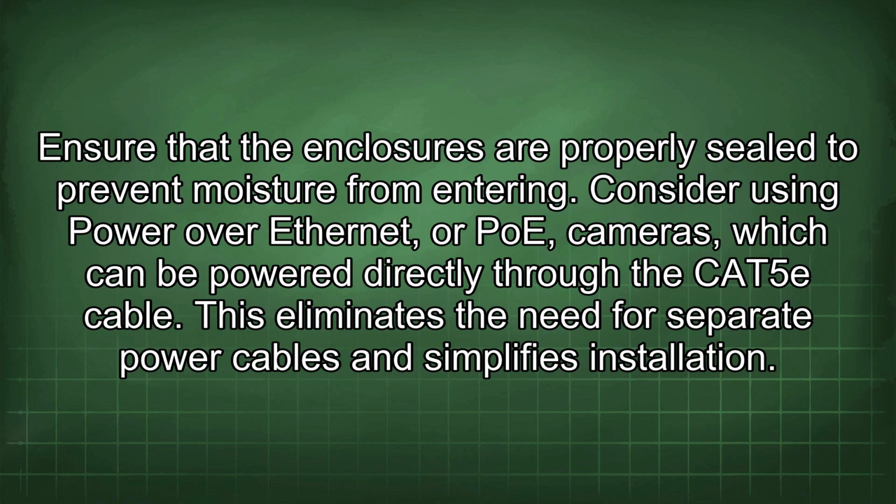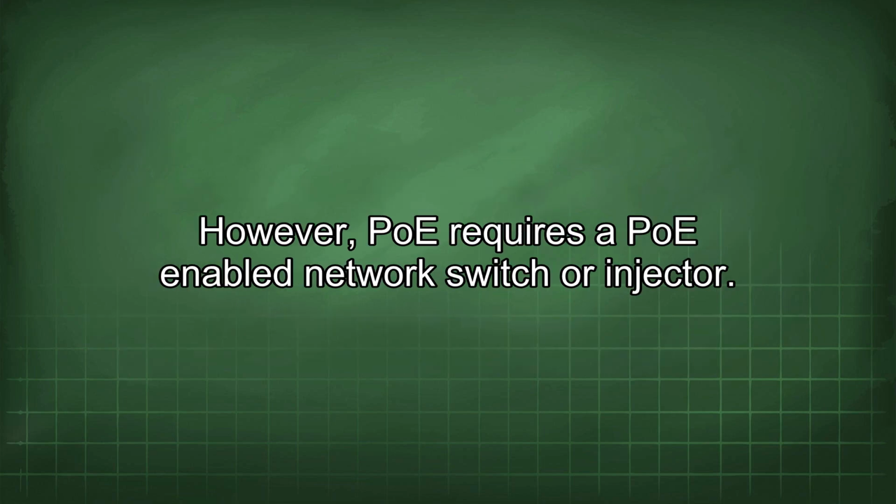Consider using Power over Ethernet or PoE cameras, which can be powered directly through the CAT5e cable. This eliminates the need for separate power cables and simplifies installation. However, PoE requires a PoE-enabled network switch or injector.